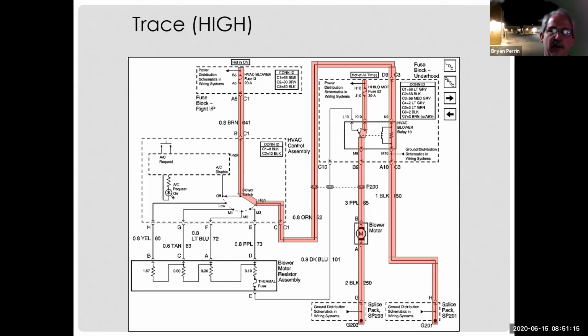If I can't complete a circuit, I can't drop voltage because I'm not flowing current. Did that help, Gabriel? Fine. Yeah, because we're still connected here, but I'm connected before we drop voltage. And therefore, since there's no current flow through these resistors, we can't drop any voltage through them. If I'm feeding the power in right here at position M2.